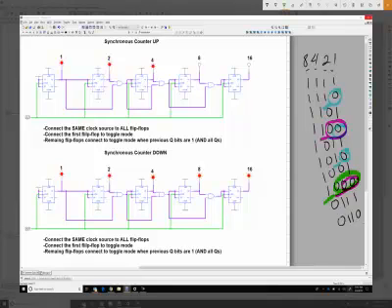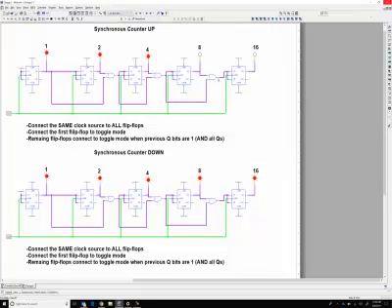So it's the same concept as what we did with the counting forward, but instead of checking that they're 1, we have to check that they're 0s. So let's do that. Some of you may be thinking, oh, just put an AND gate or NAND gate. But that would not be right, because we're not checking that they're 1 and then inverting and giving JK a 0. We're not doing that. What we need to do is check that they're 0 and then ANDing. So it's kind of like a NOR, but that's not what we're going to do. So I think it's just easier to add inverters or connect to the not Q's.